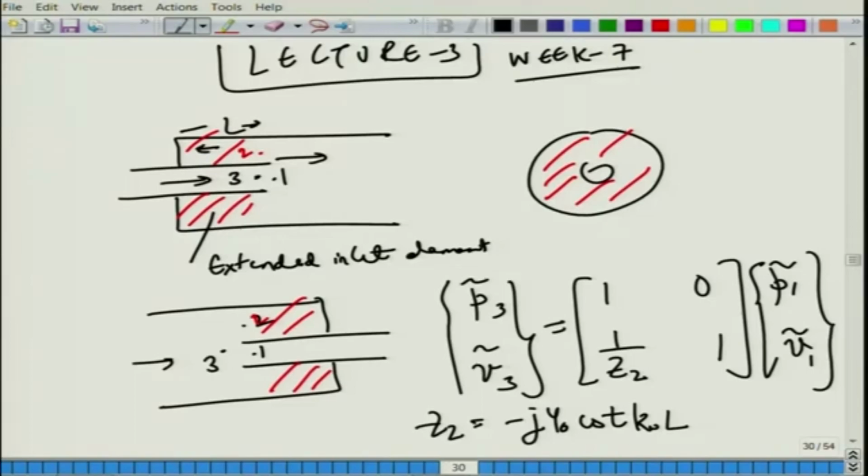However, when we do have flow, things would be a bit different, and we will see how to incorporate the flow losses that happen here. We are going to talk only in terms of a qualitative discussion, because a quantitative discussion would involve CFD simulations to simulate the flow field in such a cavity. Because a real fluid has viscosity, when flow comes in here and goes out, there will be a potential core, as we discussed at the beginning of this week's lecture, and vortices will be shed, and it will create some noise.